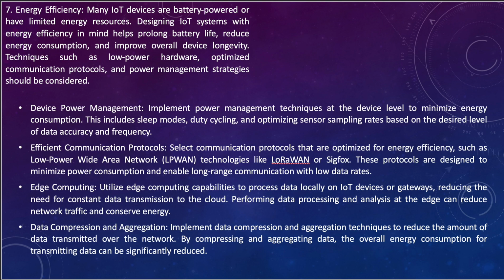Efficient communication protocols. Select communication protocols that are optimized for energy efficiency, such as low power wide area network, LPWAN, technology like LoRaWAN or Sigfox. These protocols are designed to minimize power consumption and enable long-range communication with low data rates.